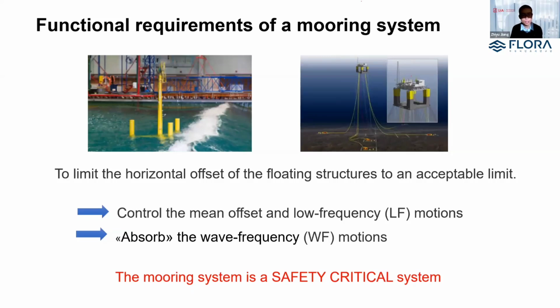The mooring system will take the mean offset and the low frequency motions. But the wave frequency motions, we can regard as the quite high frequency part, so we do not really let the mooring system take those loads. The platform is free to move along with the first order excitations.